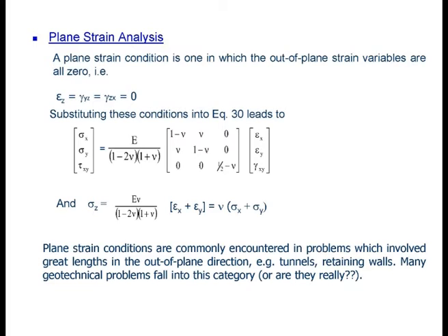So basically, supposing you have a tunnel, a lot of people say, I analyze a tunnel as a plane strain. That is a basic assumption. You know what is the basic assumption? Firstly, the soil condition is completely uniform throughout the whole length of the tunnel, which obviously it is not entirely. Maybe it is fairly uniform, it's still okay. But the other big assumption is, when you dig a tunnel, suddenly this whole thing went empty at one go, from plus infinity that direction to minus infinity. It cannot happen. You got a tunnel boring machine. You got a heading.